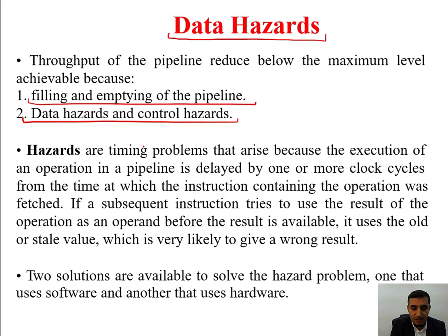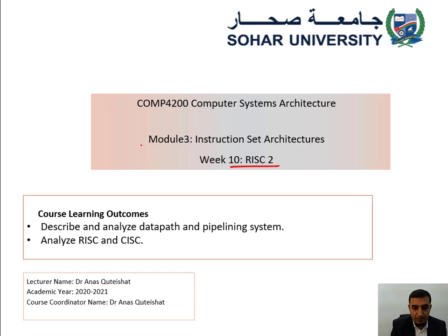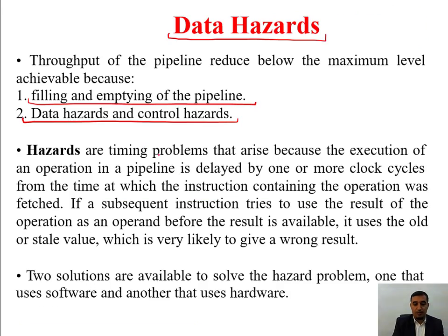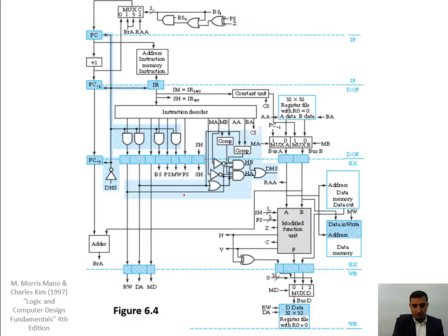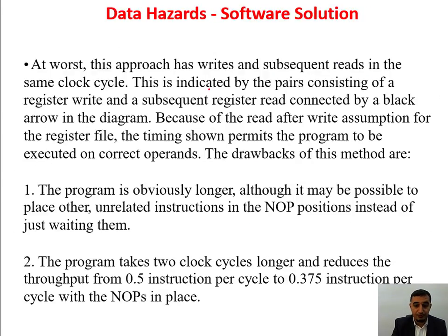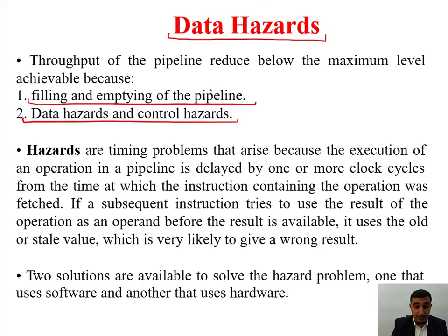Of course, structural hazard is not possible in our pipeline. Why? Because in our pipeline, we have the data and the instruction memories separated, so we will not have that problem. So the hazards that we are going to talk about are basically data hazard and control hazard.